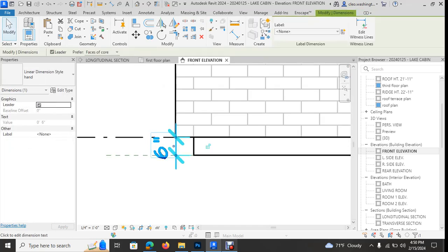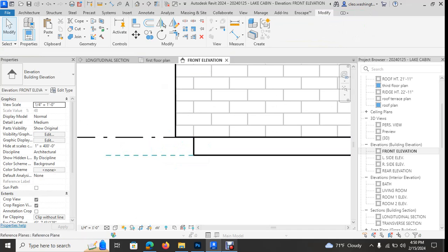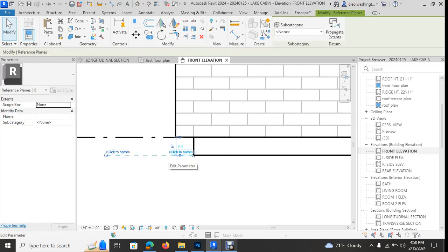Typically you build a building foundation up, but the way Revit models, you have to actually put the walls up and then you put the foundation in. We did put the floor in, but we didn't put the structural foundation in, simply because I don't want to take you guys that far just yet. We will get into that when we start our next model in 2 weeks.